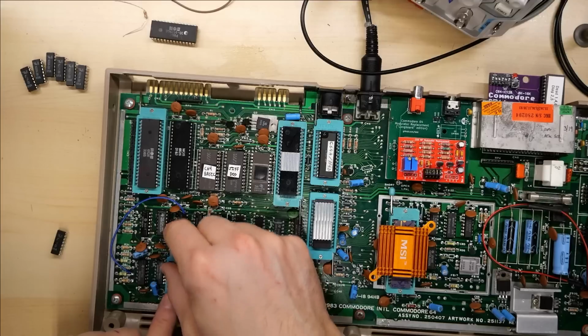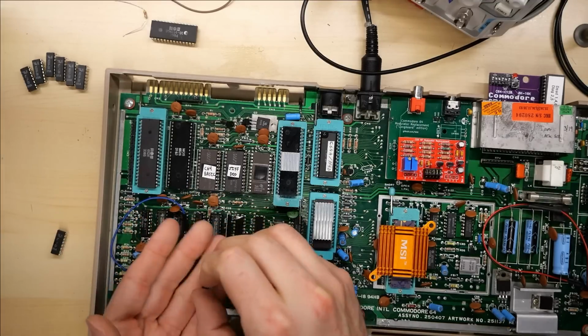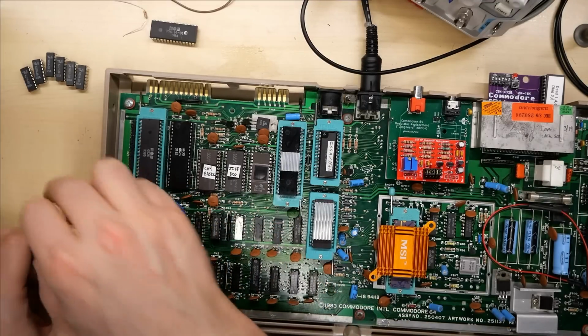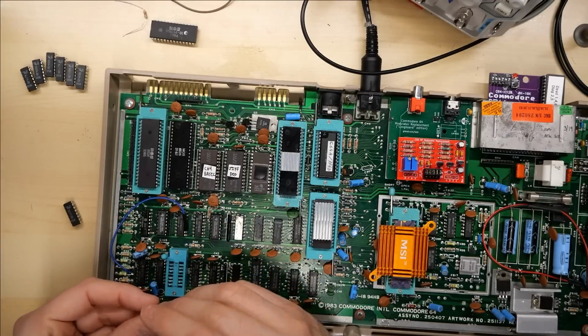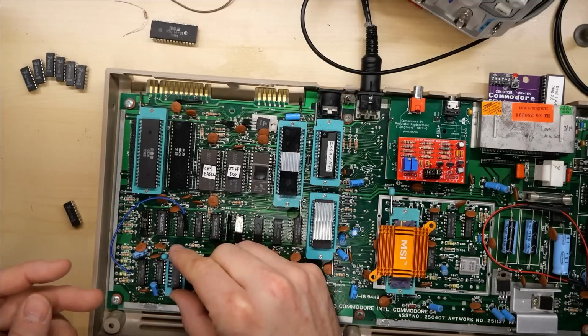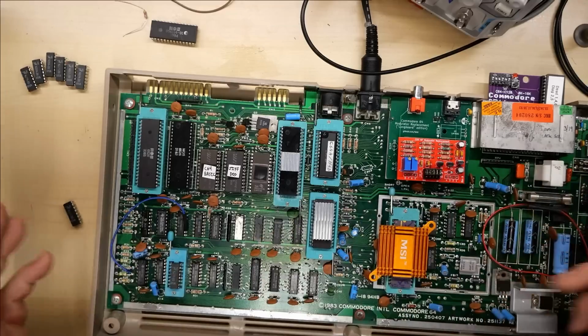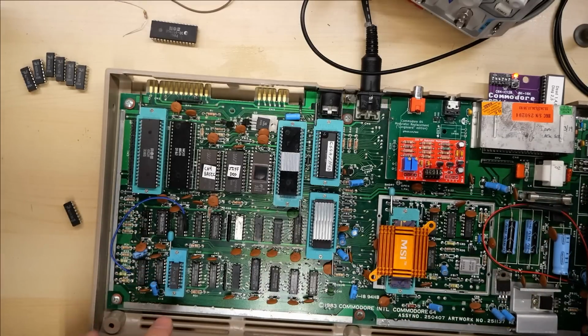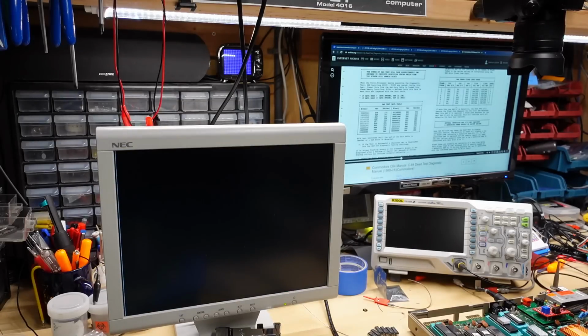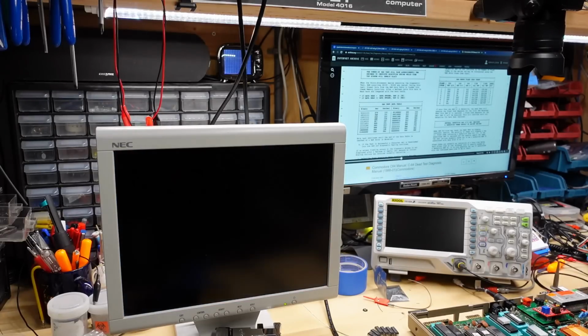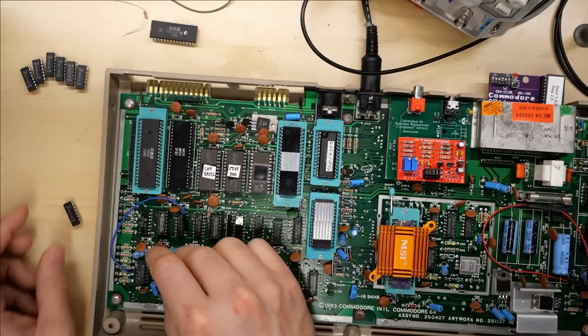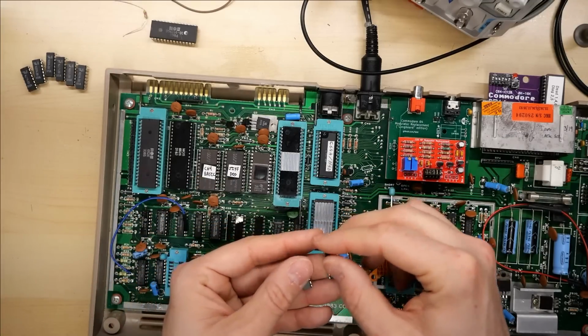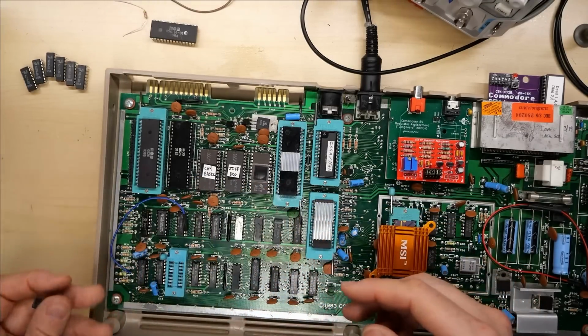So at least in this case, if one chip were bad, dead test would have directed us to the bad chip. Of course, originally on that machine, the other machine had a bad PLA. You're not going to get any kind of dead test activity with a bad PLA. I'm sticking in the other bad RAM chip. Let's see if we still get 6 flashes. 1, 2, 3, 4, 5, 6. We do. Excellent. So in this case, dead test would have been successful at detecting these RAM chips.